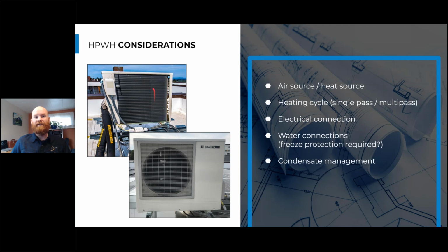That condensing fluid turns into condensate and drains out. Typically, there's a condensate drain pan on the bottom of these units, and we can connect a pipe to that to take it to an appropriate location. If we put these on a rooftop and it's making condensate, and then that condensate freezes, we're going to create an ice skating rink for the maintenance personnel. I'm not sure that's the best approach, so it's definitely some consideration that we should be thinking about.